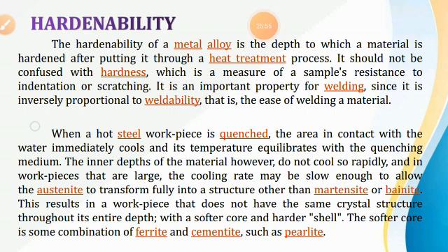Hardenability is nothing but the depth to which the material is hardened after putting it through a heat treatment process. At what depth the material is hardened. It should not be confused with hardness, which is a measure of a sample's resistance to indentation or scratching.